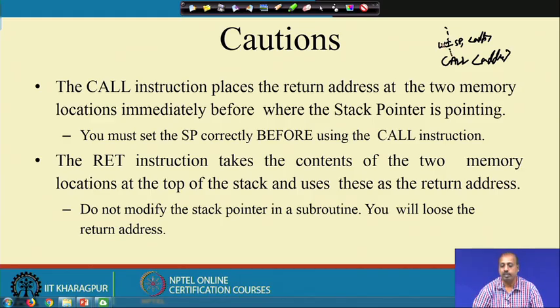So, if you do not execute the LXI instruction, then this call will also execute, but the effect may be disastrous. It may corrupt other values or data of your program, because the stack pointer points to arbitrary locations, and then it tries to write the program counter value there. So, you must set the stack pointer correctly before using the call instruction.